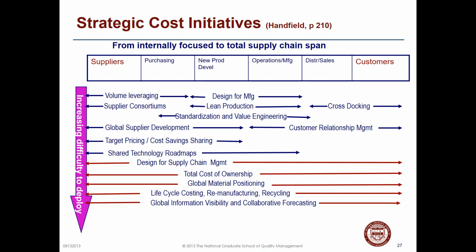Any reduction in the bill of material for any product will save money. Any standardization of that bill of material will also save money. Don't go with different size bolts and nuts, screws. Standardize the hardware as much as possible. Again, you'll save money. And then look at all those life cycles within your remanufacturing cycle.